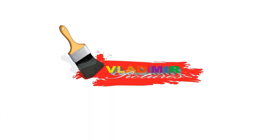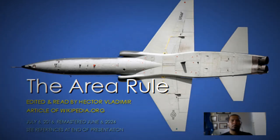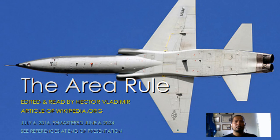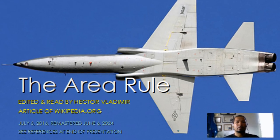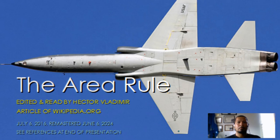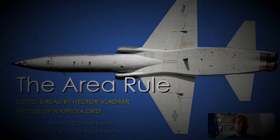The area rule. The Whitcomb area rule, also called the transonic area rule, is a design technique used to reduce an aircraft's drag at transonic and supersonic speeds, particularly between Mach 0.75 and 1.2. This is one of the most important operating speed ranges for commercial and military fixed-wing aircraft today, with transonic acceleration being considered an important performance metric for combat aircraft and necessarily dependent upon transonic drag. A quick description on the subject.